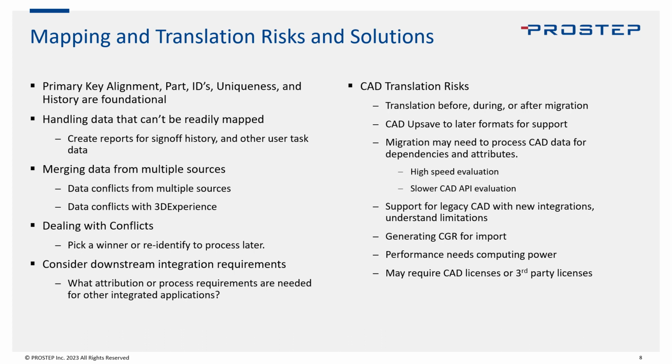CAD data upsave is also generally a thing that's pretty popular within migration. So CAD integrations don't always support all those legacy CAD files that you have. So you have to have a mechanism to load it into a preferred format that you can then use, and that might be upsaving your SolidWorks data, upsaving your Creo data, something like that, to a later format that's then supported within the application.